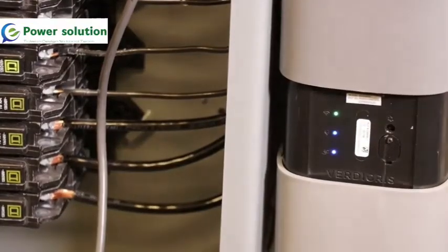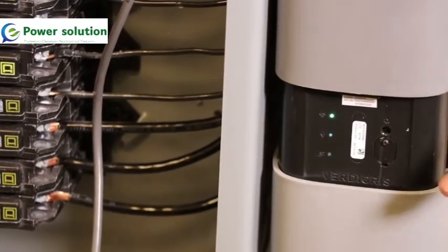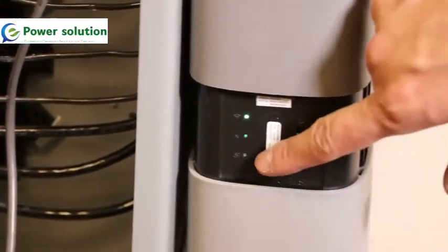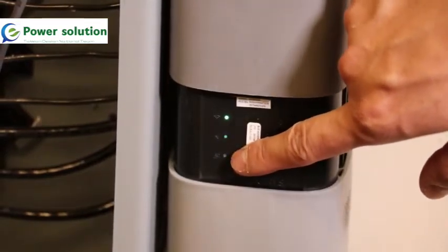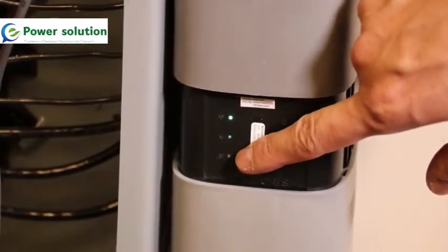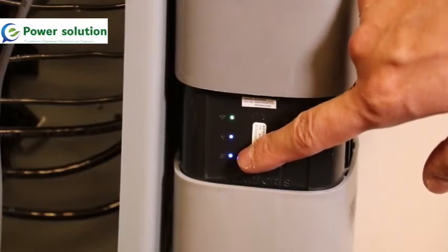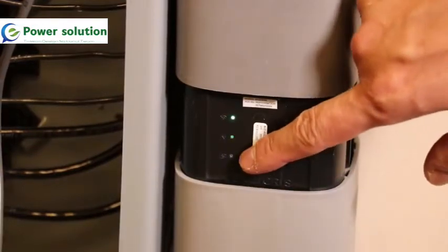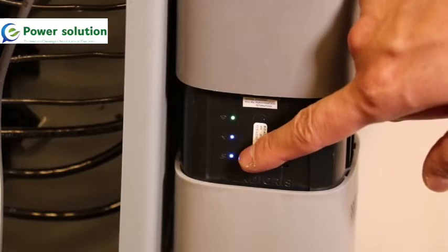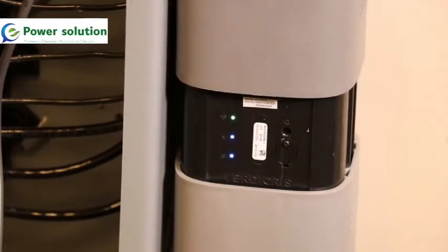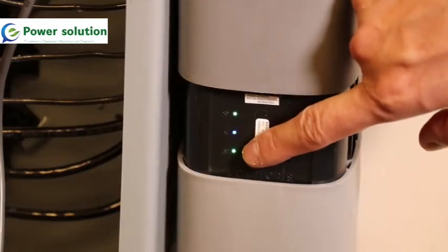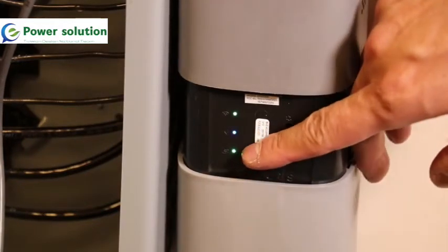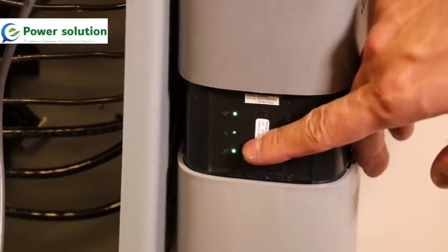So after your CTs go through their self-check, you'll want to see this chain light go green. And once this light goes solid green, that ensures that the chain is physically connected. If this light goes red, you'll want to check the continuity of your chain, and we'll look at the light code for that in a second. You can see in this run, the chain light has turned green, so our chain is continuous.